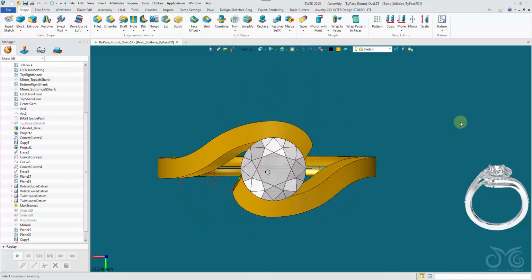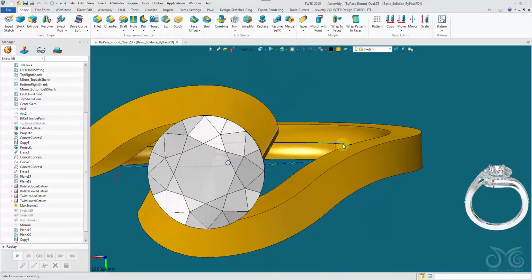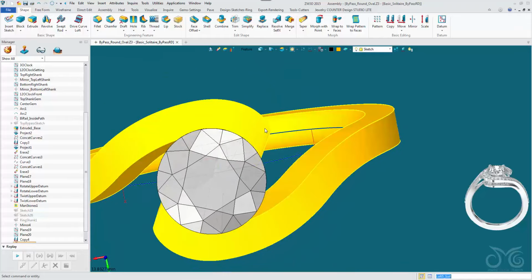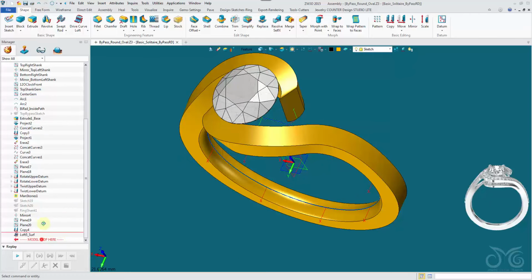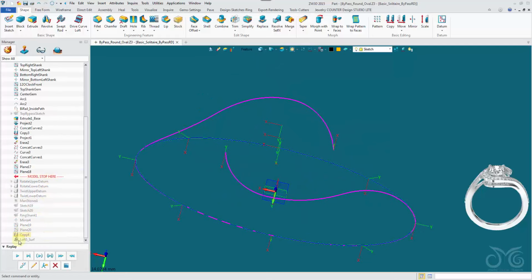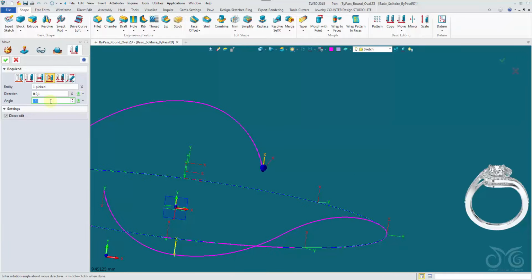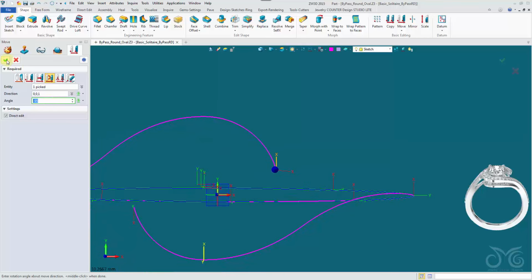A smoother transition. Still not perfect. So what I think I want to do, for one, I want to rotate these end datums so that this side comes further around. So I'll come back into, I think they were the rotate. I'll edit the rotate, it's this one here. I'm going to increase this rotate quite a lot. So 90 would be, let's say 95 degrees.